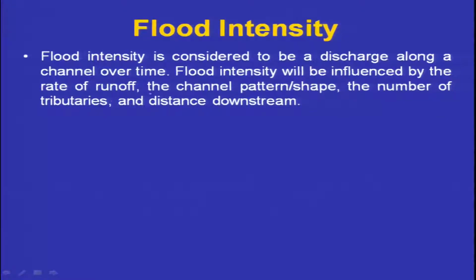The channel pattern and shape will also play a role along with the runoff. The number of tributaries, that is what we were talking about, the bifurcation ratio, as well as the drainage density and the distance. So, when you are extracting information about any drainage basin, this can be kept in mind. This can help you in saying whether this area will have higher floods, and whether the intensity of the flood will be higher or lower.